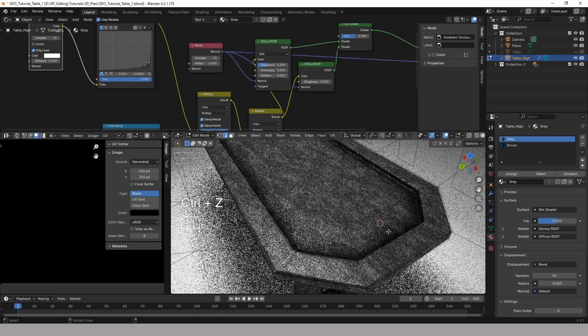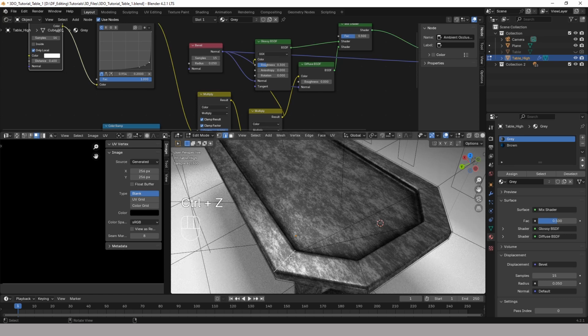The other really handy thing about Blender's edge loop cutting tool is, again, select that edge, Control R, and then use the mouse wheel. You can just put in as many extra loops as you want. This is a very efficient way of modeling, and it's particularly why a lot of long-time Blender users will favor the keyboard shortcuts over the gizmos, because once you start combining a lot of those shortcuts, it just makes things way, way faster.